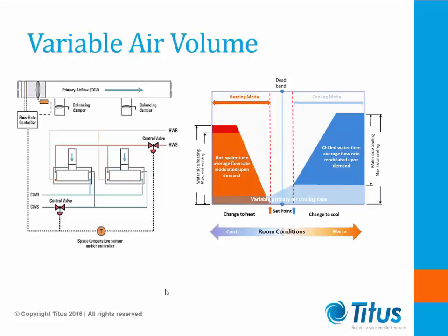Chill beam systems can also have variable airflow. In these cases, the primary method of space temperature control is still going to be the zone thermostat regulating the water flow to the beams from the chill water or hot water supply load.